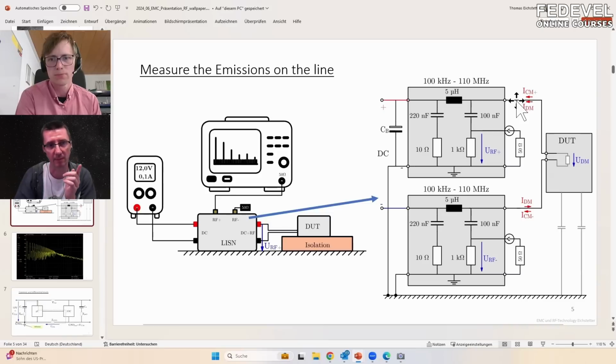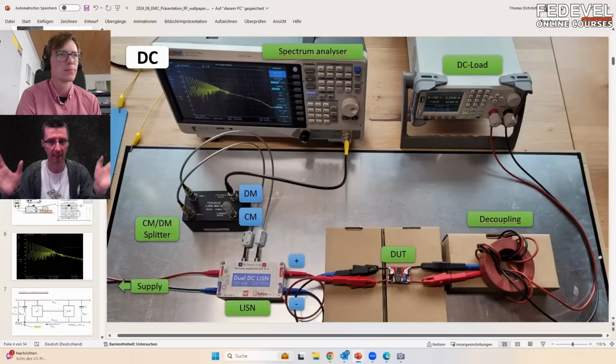So this is very important, because I think many people may think all the currents only flow through the wires which are connected to your power supply, but that's not true. Currents go always in circles, always, even when you make an ESD test. Okay, so that's also why we need this big metal plane, so we can do the correct measurement. When you go back to your picture, so everyone who is doing this kind of measurement, they also need this big ground plane.